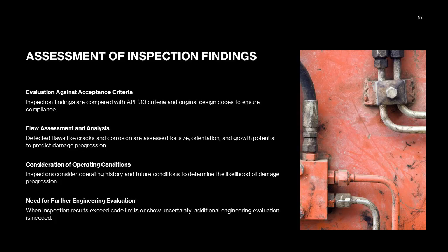Assessment of inspection findings, fitness for service, and inspection intervals. After inspection activities are completed, inspectors must evaluate the findings against the acceptance criteria defined in API 510 and the original design code. Measured thicknesses are compared to the calculated minimum required thickness to determine remaining life.